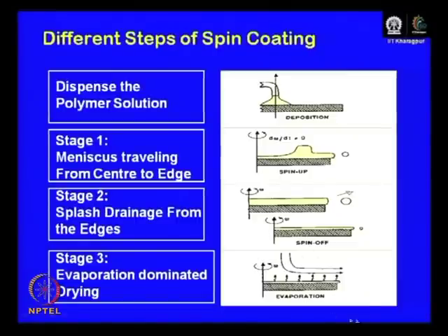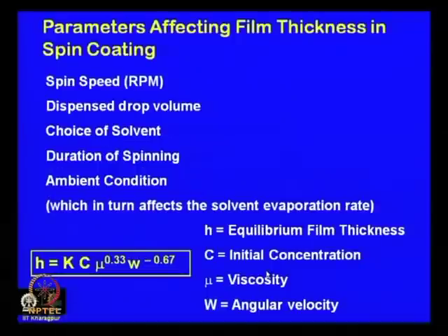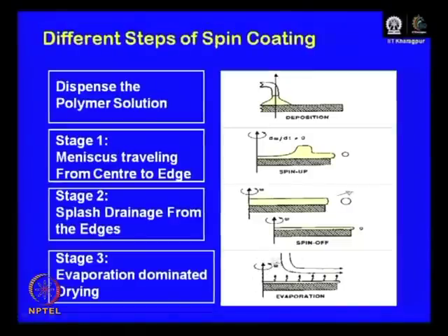Based on the surface energy balance of the system, the film might actually retract or rupture at different locations. However, if you allow the spin coating process to continue significantly, so that you reach the evaporation dominated regime, then whether you spin it for 1 minute or 5 minutes really does not make much of a difference.